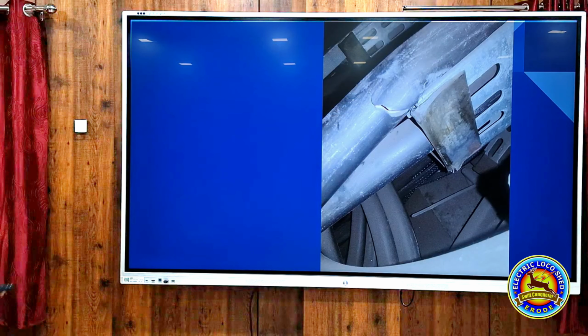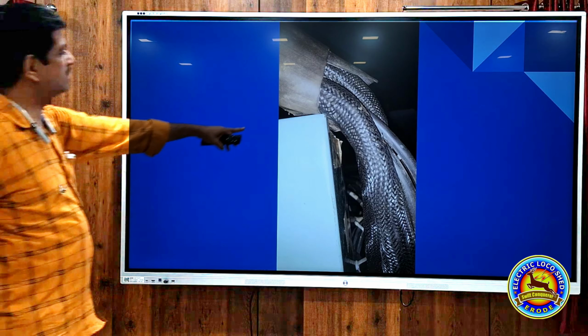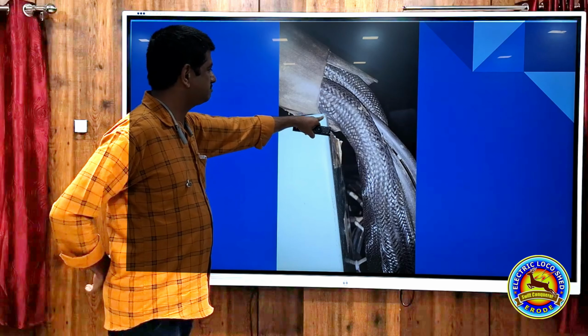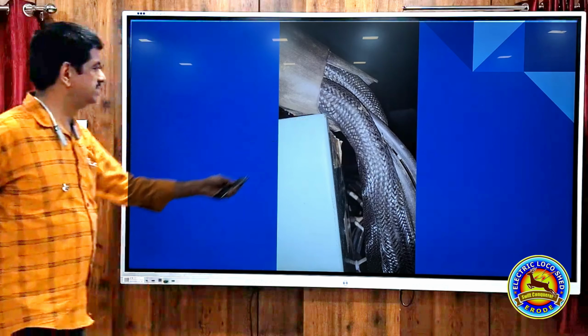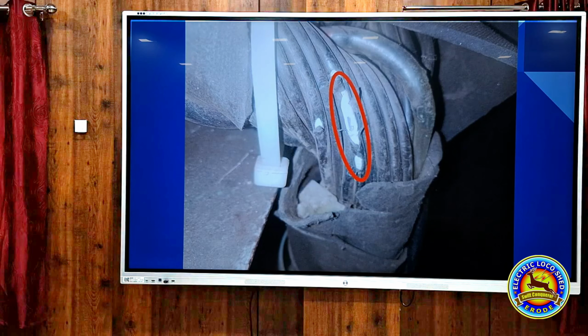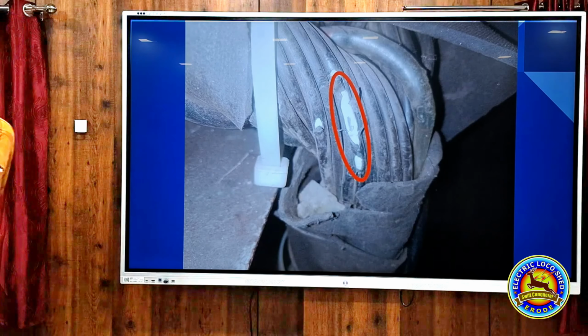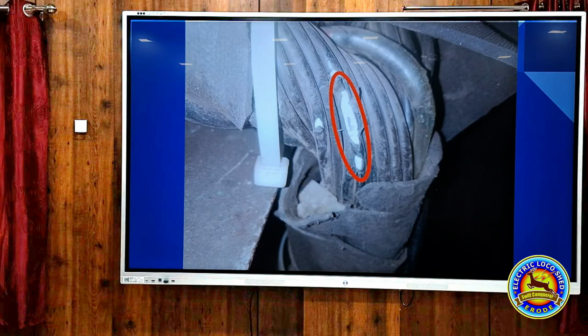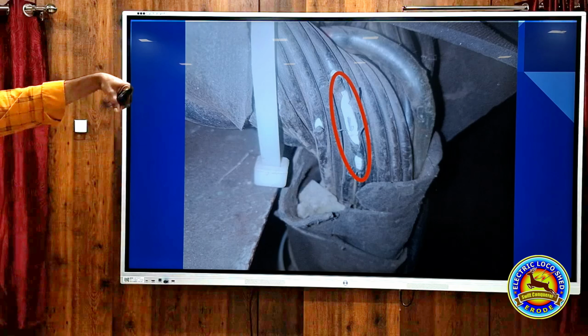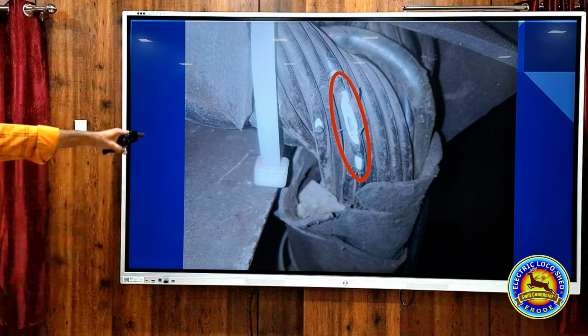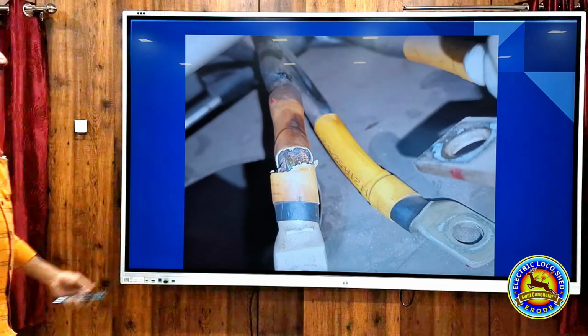This is a cable failure. In another failure, you can see one cable bunch damaged due to a sharp edge. Such cable damage may occur when an improper tool is used. For cable tie cutting and similar jobs, only a proper wire stripper should be used. If someone uses a knife or a hacksaw blade piece, there are high chances of the cable insulation getting damaged due to the knife edge hitting the cable.